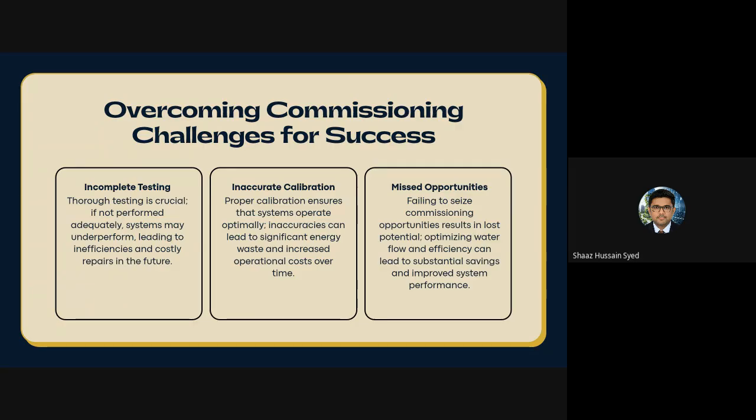If some valves are open too much and others closed too much, the water will not flow properly to the units, and that will cause the delta T collapse. Valves not turned properly, sensors not calibrated, bypass line accidentally left open, AHUs not tested. These are the common and major mistakes during commissioning, which people tend to overlook, and which cause the delta T collapse.